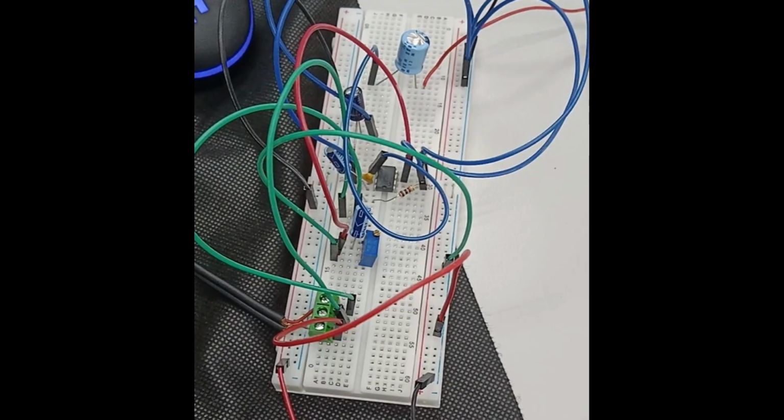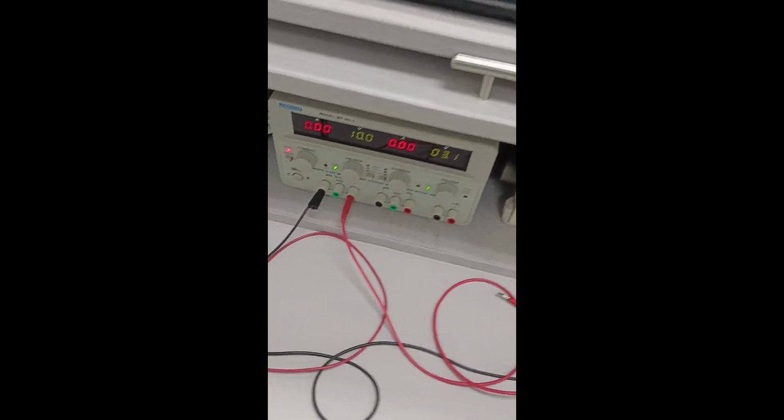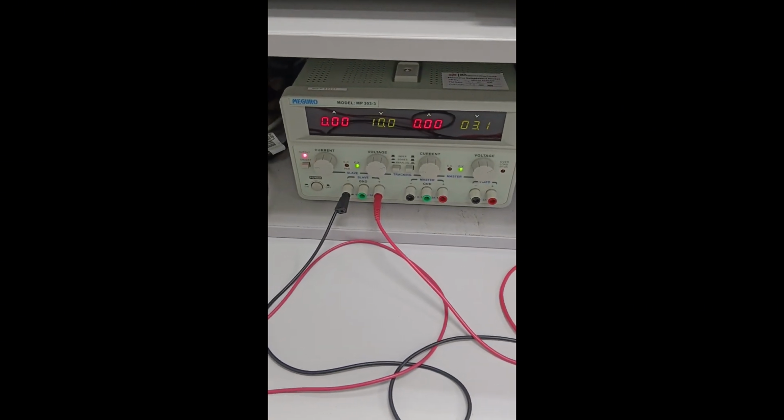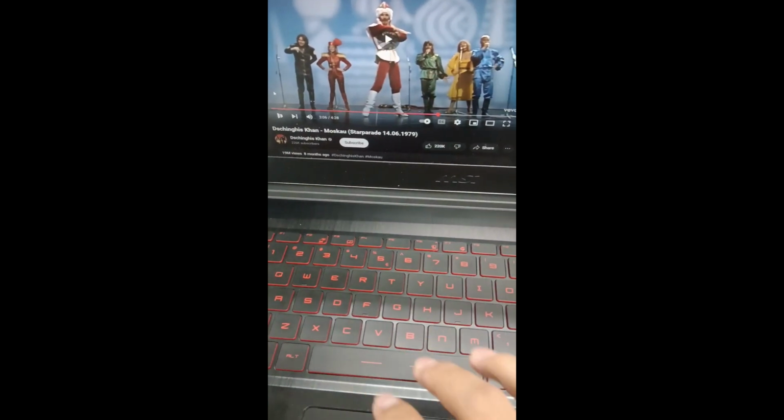And this is the first design circuit, where we found out the difference of how the capacitor will affect the outputs. Here, when the capacitance is lower than 220 microfarad, the audio will not be clear and it has a lot of unnecessary noises.